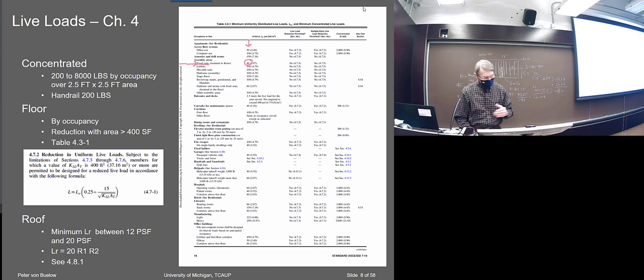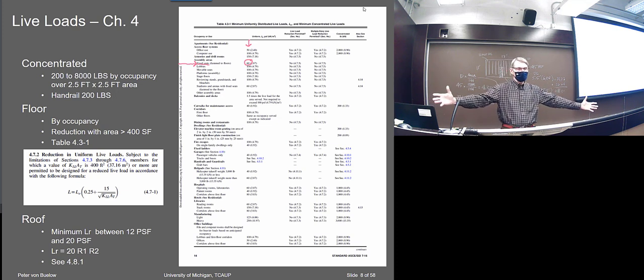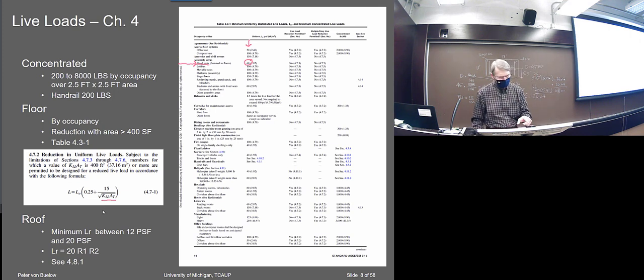This was the live load. This, by the way, gave the floor live load for larger floors, and that was not a very large floor, up over 400 square feet. There's a reduction factor because they figure you're not going to have the floor totally filled with the load. So you can work this little equation for the reduction factor. This part here, we used to call influence area. It's now just a way to calculate the influence area.